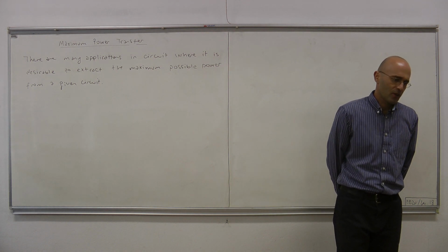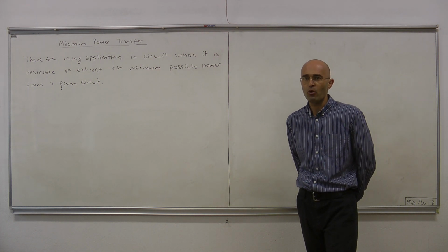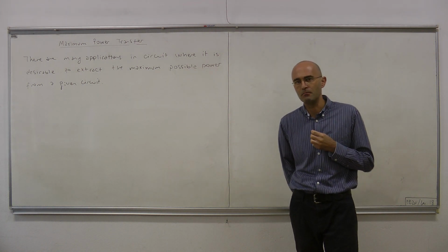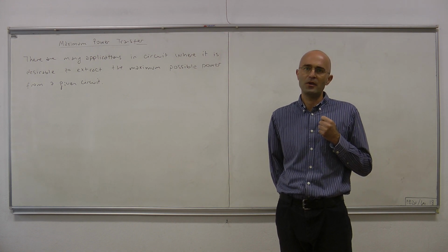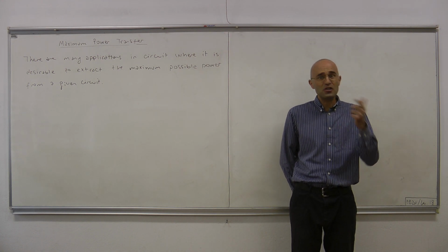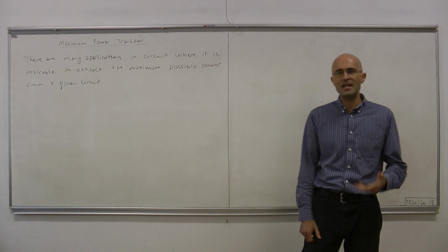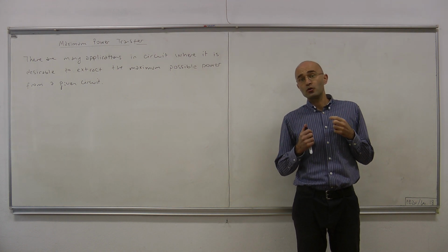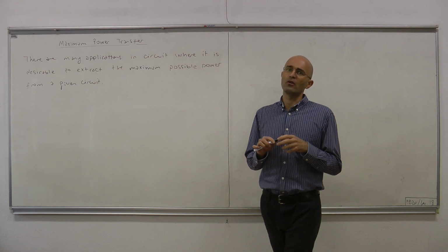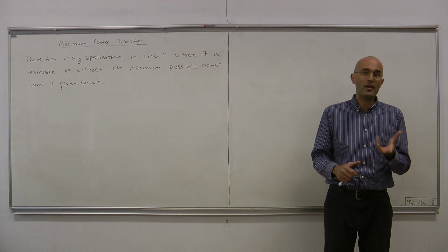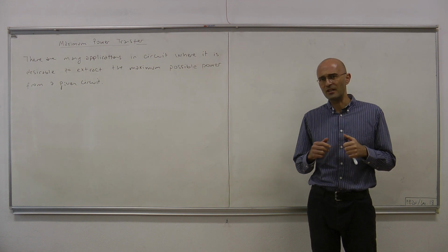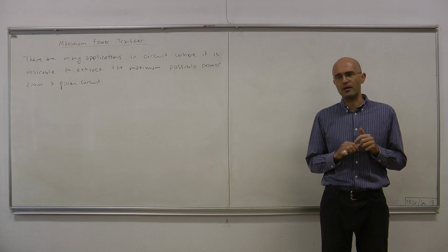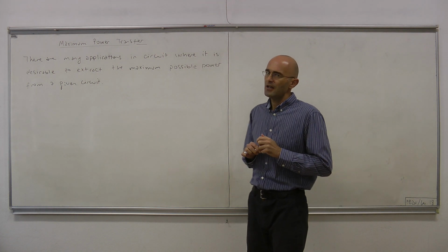Now, for certain applications, that component, from the power consumption point of view, can be adequately modeled by a single LTI resistor. In that case, the resistance of that resistor becomes your design parameter, and the problem in its simplified version becomes the following: how should I choose the resistance of that resistor so that it extracts as much power as possible from the rest of the circuit? Now, the answer to that question is not obvious.